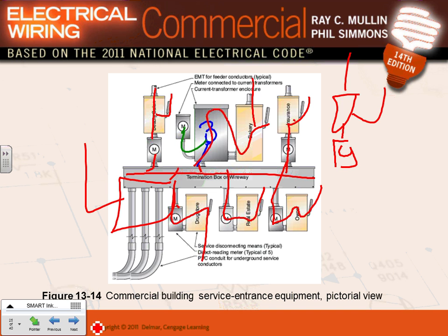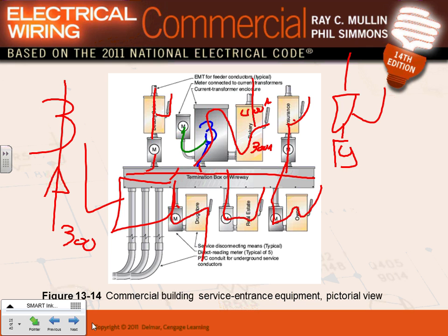For example, the bakery, this one was 300 amp. This is a 300 amp fuse with a 400 amp disconnect. So what they did, guys, let me just summarize how it goes. So here's my CT cabinet. Inside it, I have a 300 amp, and the 300 amp will come from this side of the meter and will be seen as 5 amps.